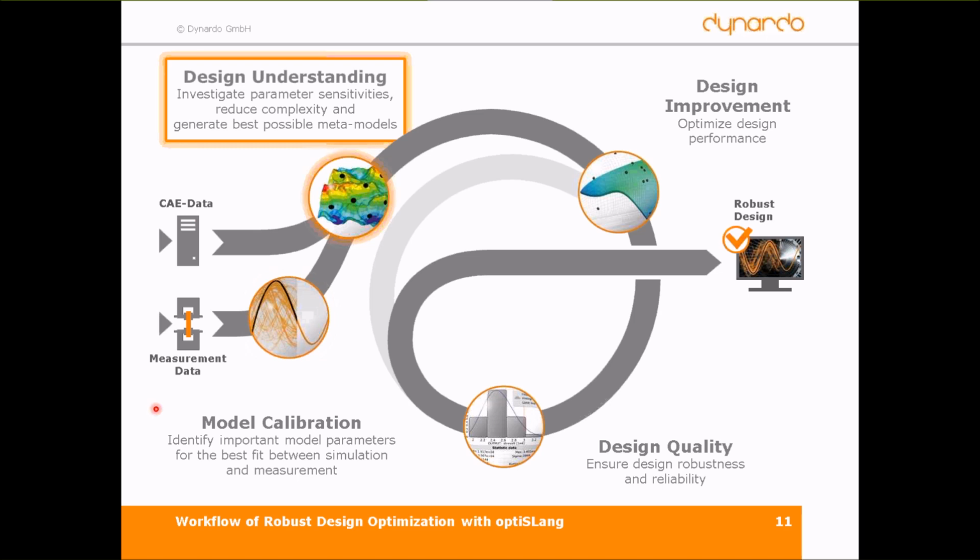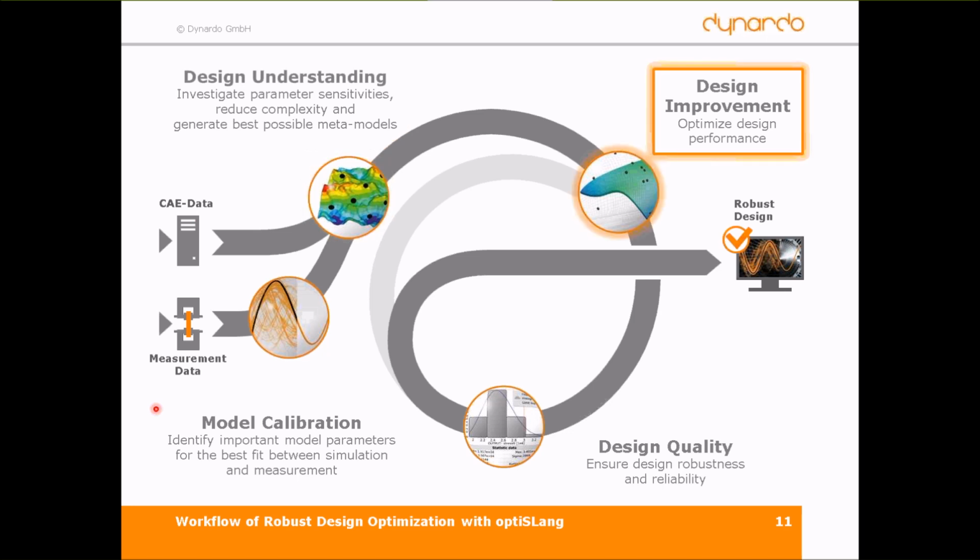Sensitivity studies mean examining how outputs react when I change inputs. Is one parameter influencing an output? Do I need the change of two parameters to influence an output? That's coupling. Is it reacting linearly? Is it reacting non-linearly? And you gain design understanding. You can get a response surface which represents the response Y depending on many inputs X. After the sensitivity analysis, you can devise a targeted, efficient optimization strategy.